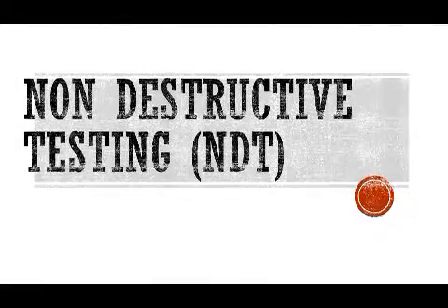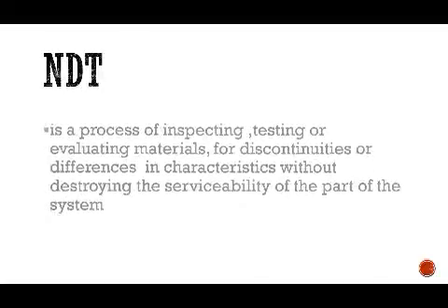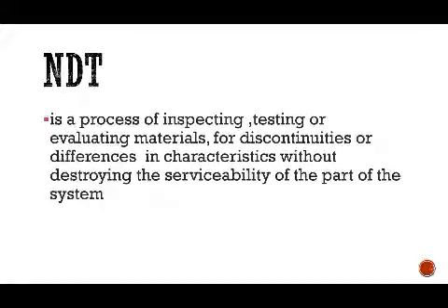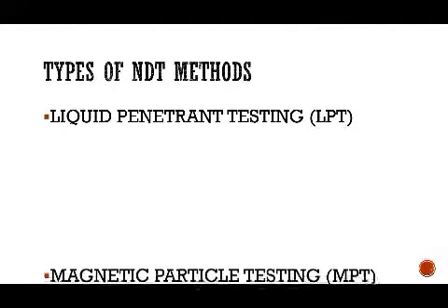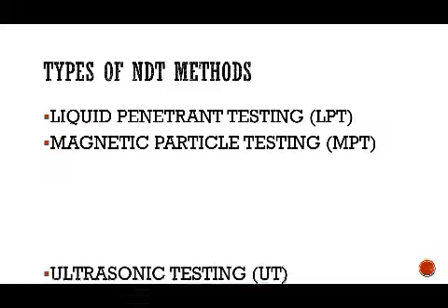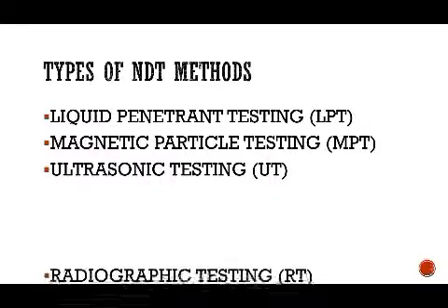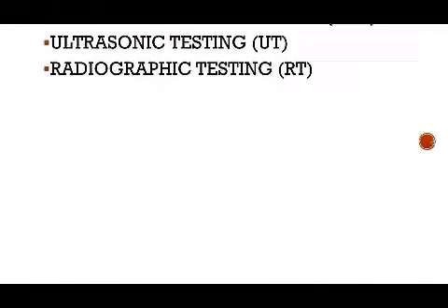Non-destructive testing, or NDT, is a process of inspecting, testing or evaluating materials for discontinuities or differences in characteristics without destroying the serviceability of the part or system. There are four major types or methods of NDT: liquid penetrant testing or LPT, magnetic particle testing or MPT, ultrasonic testing or UT, and radiographic testing or RT.